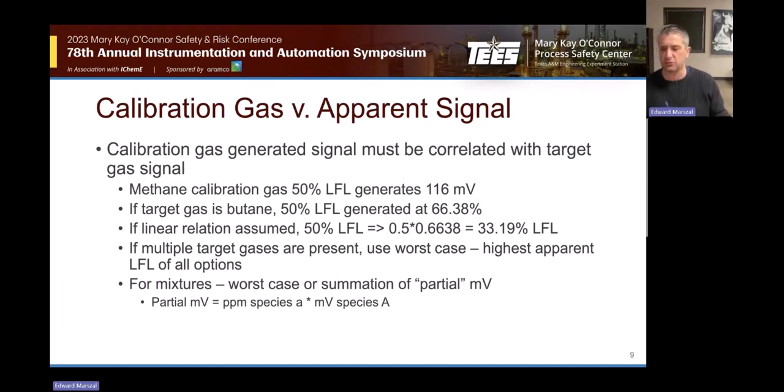So any residual naphtha we're going to knock out. And then we're going to do a depentanizer to remove your pentanes, debutanizer to remove the butanes, depropanizer, and so on. So you're splitting that gas potentially, depending on your configuration, into multiple different gases.